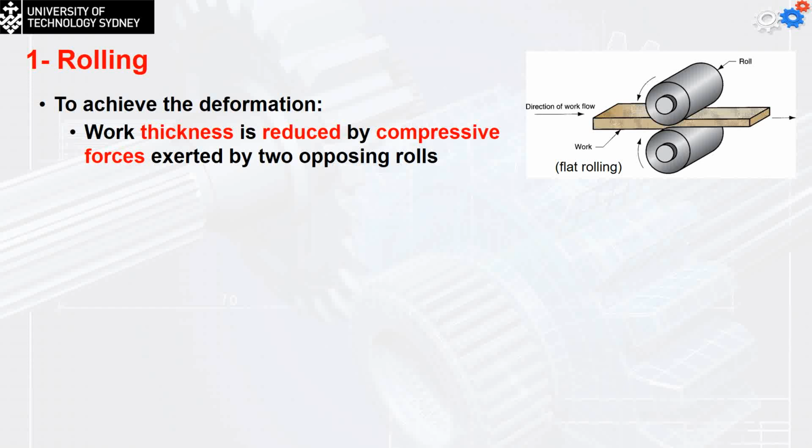Now, because the part is going to get thinner, we must know that the volume of the part is constant. So what's happening if it's going to be constant volume, but now the section gets thinner? So what's happened? Something decreased, so something else should be increasing. Yeah, the width and the length. Yeah, the width and length are going to increase, thus the volume is going to be constant.